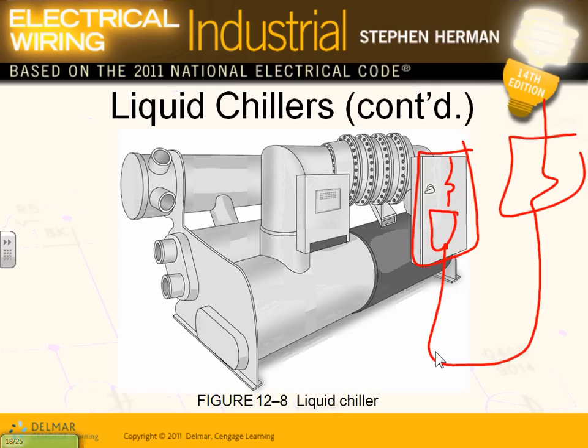And the rest of it is bringing the cold water, keep chilling the water and circulating that water through pumps. You can see next to these will be multiple pumps sitting there and circulating this chilled water all through the air handling unit or units, and bringing it back as hot water to the chiller again, and keep doing the whole cycle.